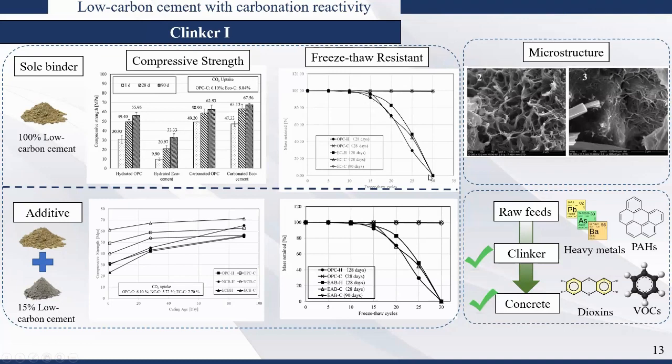After 30 freeze-thaw cycles, all the reference batches dissolved, and the mass retain becomes 0, which means all the concrete dissolved, like in the water. But using our material and through carbonation, we found that it's barely damaged after 30 cycles. So it shows a very good durability performance.